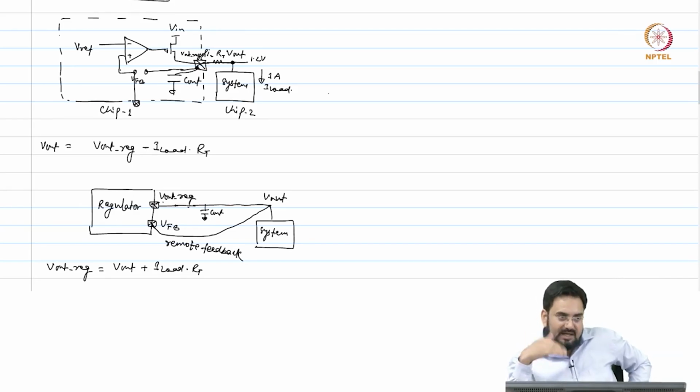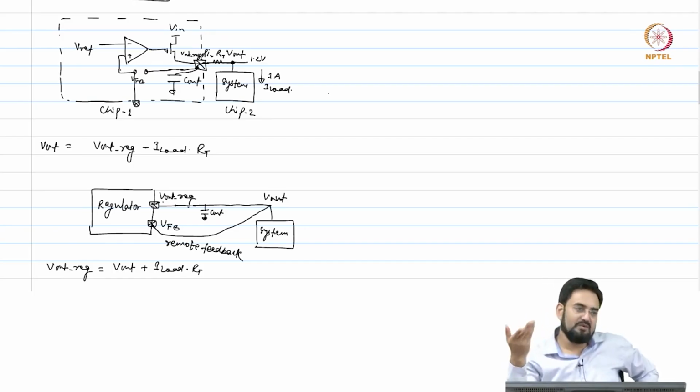Yeah, you can slightly move the Vref, but you need to know the resistor value, all the drop. So, if you know that your current is fixed and your R is known, you can calibrate also. Initially you can measure and see if it is coming 1.2 volt or not. So, you keep on changing the Vref until your output becomes the desired value. So, you may have to calibrate, and you may need a very fine regulation, depending upon what accuracy requirement. If you want within 1 millivolt, then you have to change your Vref by 1 millivolt step.